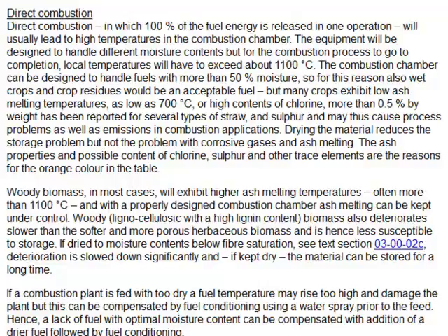have low ash melting temperatures, and depending on how the combustion chamber has been designed, this may lead to operational problems that may be more or less severe. In contrast to that, woody fuels typically will have high ash melting points unless they are too contaminated by soil and other extrinsic contaminants that may have entered into the fuel fraction during the supply chain.